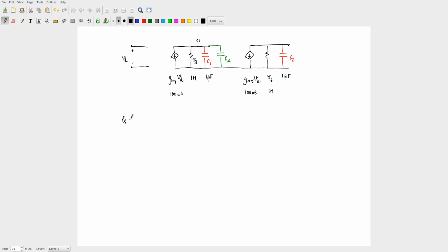So when zeta is equal to 1, we calculated what P1 and P2 should be. There is a relationship between P1 and P2, and what is that? P2 must be equal to 4 times the unity loop gain frequency, which is A0 by K times P1, right? This is what we had already calculated. All right. Now if I add a C alpha like this, does it alter my P2? No, right? It is only changing P1. So now can you go back and calculate?